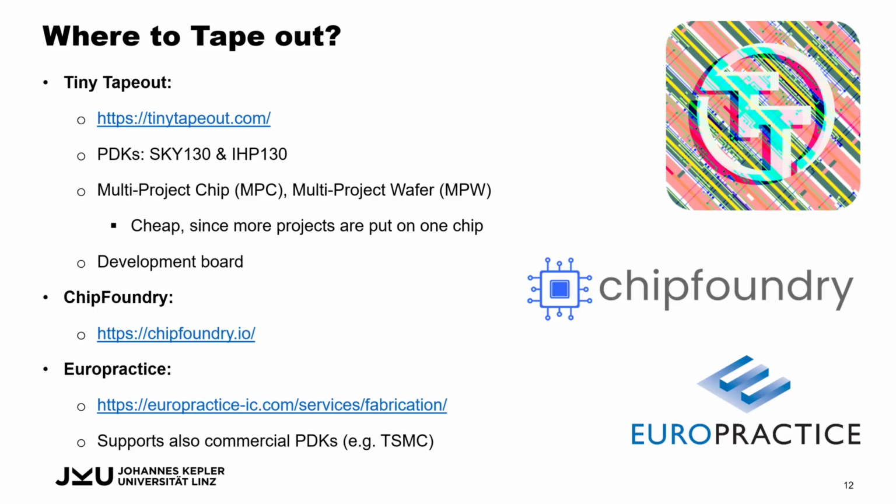And then we have Europractice, and I think Europractice is doing the multi-project wafer approach. And you also can tape out commercial PDKs there, for example, TSMC with really flagship PDKs down to several nanometers. But of course, these tape outs are then quite expensive.